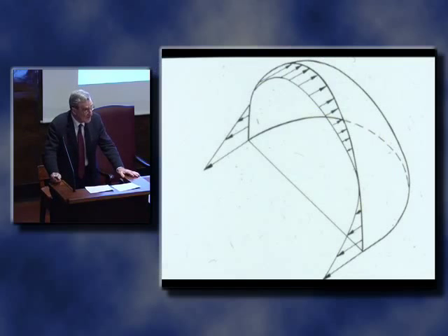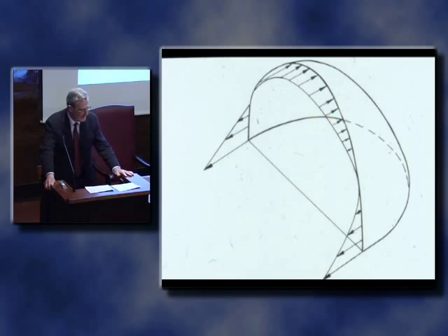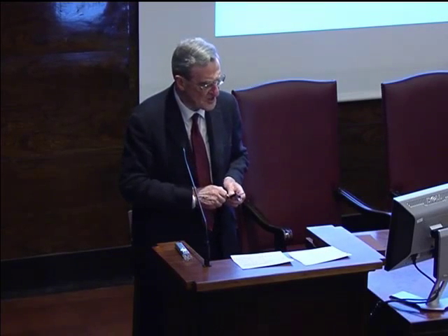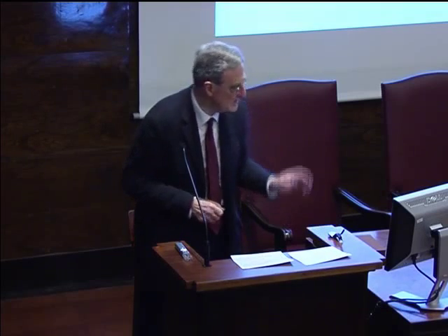And this is not admissible, therefore, for a solution if we are looking at a masonry dome, which cannot take tensile stresses. Something has gone wrong with our analysis, with our assumptions perhaps, and this is where one must begin to look at the beginning assumptions of the whole theory. We have assumed that our membrane has zero thickness, and so the forces are compelled by the geometry of the sphere imposed in this way.